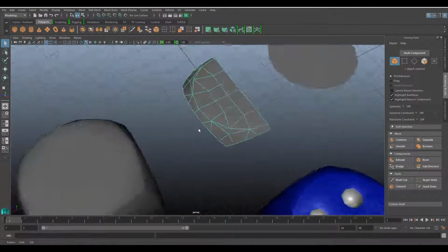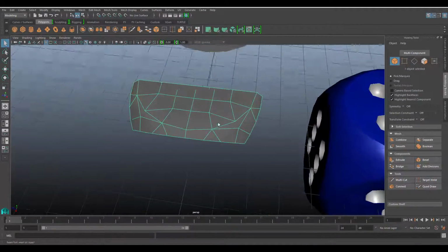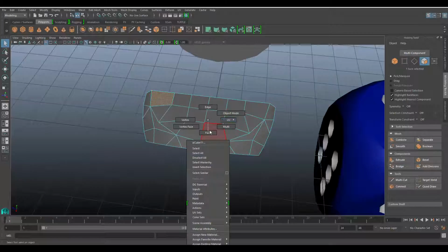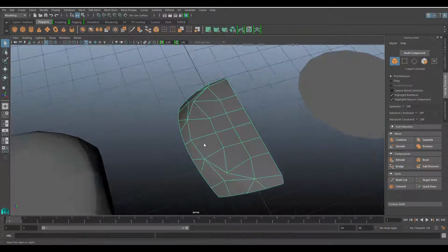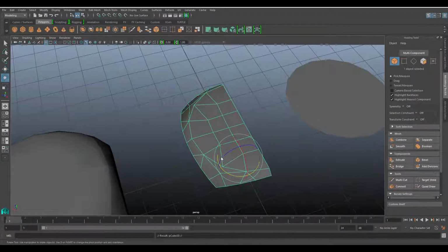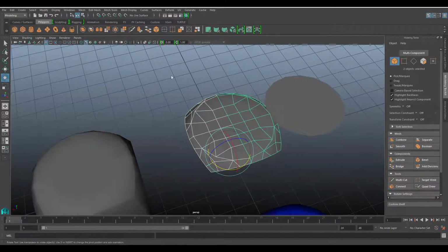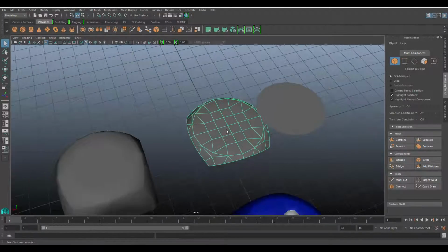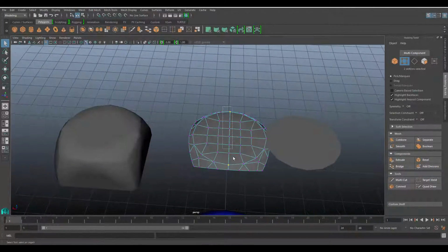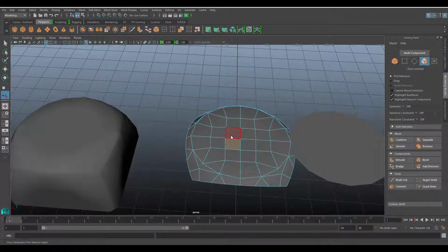Alright, so in order to make the faces, what we want to do is go ahead and take our section of the dice, duplicate it around, go to Mesh, Combine, select the vertices, weld them together. This will create the solid top that we're going to need to make our dimples with.